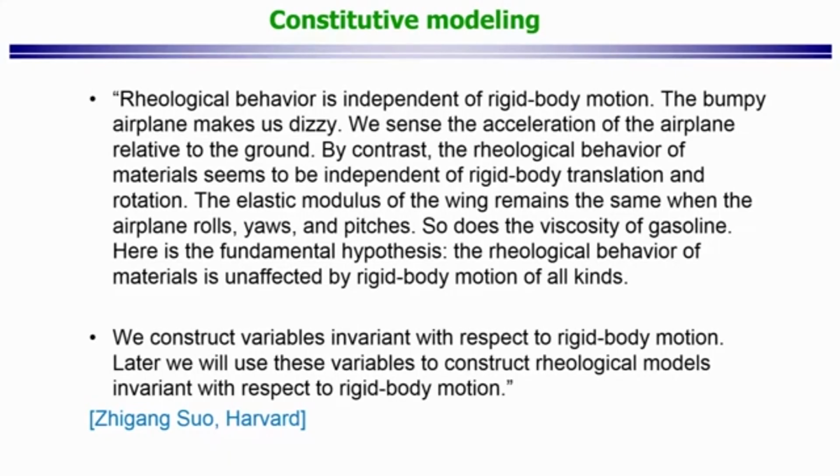The elastic modulus of the wing remains the same when the aeroplane rolls, yaws and pitches. So does the viscosity of gasoline. Here is the fundamental hypothesis: the rheological behavior of materials is unaffected by rigid body motion of all kinds. And then he goes on to say later that we construct variables invariant with respect to rigid body motion. Later we will use these variables to construct rheological models invariant with respect to rigid body motion.